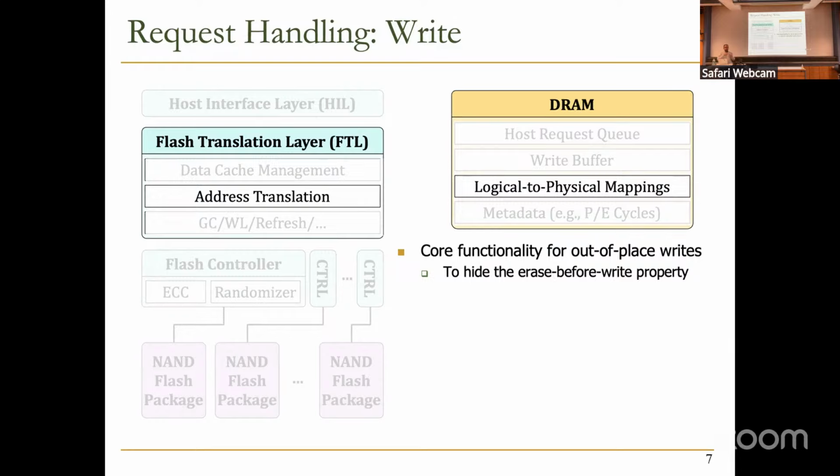You need to move them, for example, to an internal DRAM, and then you update that specific page inside the DRAM, and you erase the whole block, which is hundreds of pages, and then you write everything back. Okay, so that's the update which could happen inside the flash chip if you want to do in-place updates. And you can guess now why we don't do in-place updates. So in flash chips, we do out-of-place updates.